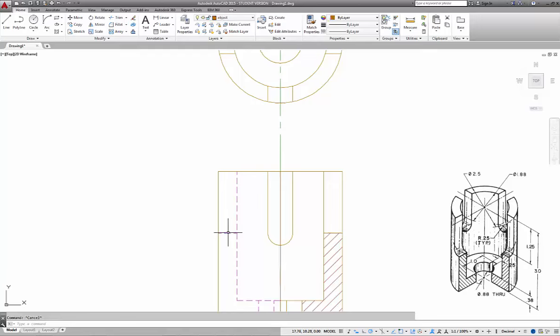So I grip this object, pick the center so I can move the whole line. But I want to move the whole line based on this intersection. And so I need to bring that intersection point straight across and make sure it's perfectly vertical. So what am I looking at? I'm looking at the numbers, polar 270, intersection 180. Is that a 90-degree intersection? Absolutely. Make sure you don't touch the mouse or breathe on it, because if you move it, it's going to change the angle. And very lightly left mouse click. Congratulations, you just shifted that down.